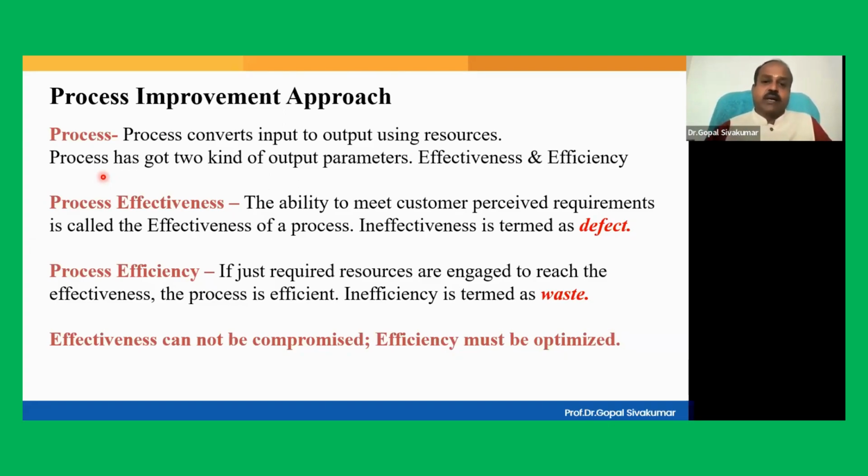Some companies straight away call it rejection percentage, because rejection percentage is nothing but 1 minus your yield, right? If your yield is 90%, rejection is 10%. So ultimately, all of them give the same interpretation. Sigma level, yield, rejection, PPM, DPMO, CP and CPK are all interconnected. If you understand the relationship, you can use any metric, right?